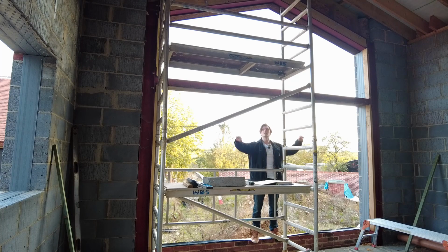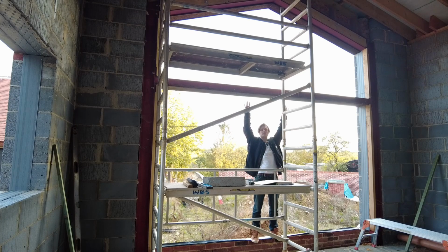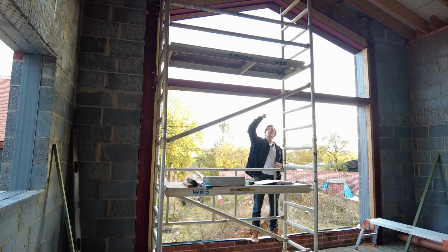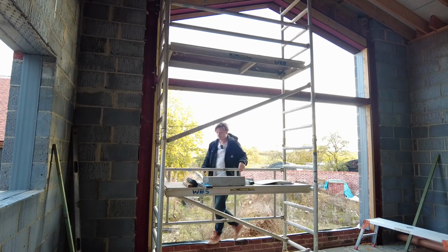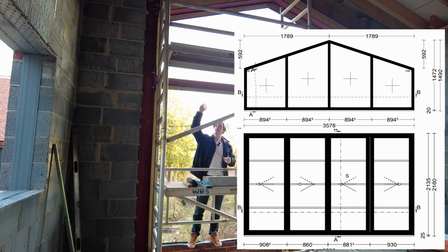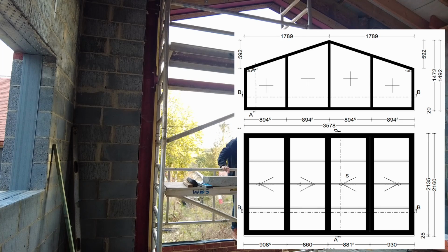So if you imagine, I'm going to have mullions up top as well. That one right at the apex is not going to line up with this one in the center. For me, that works out, it's going to be 20 mil offset. These ones here, if I just left it, then it would be, I think, 60 mil off center for that side, and it's less for over there.